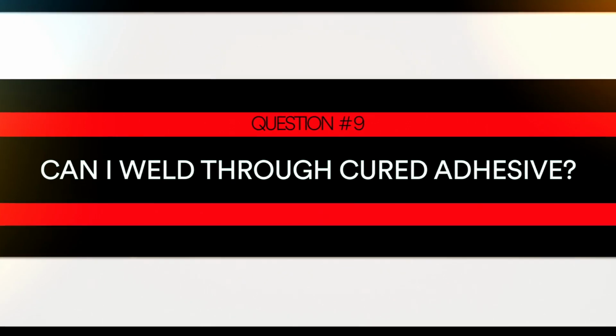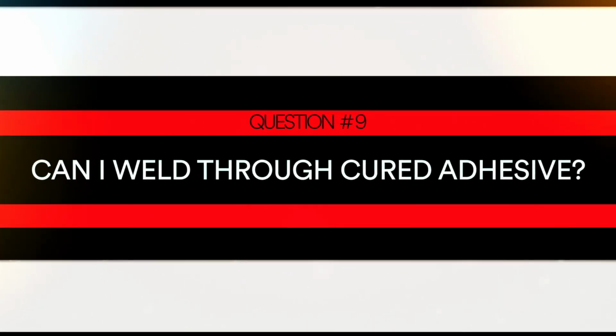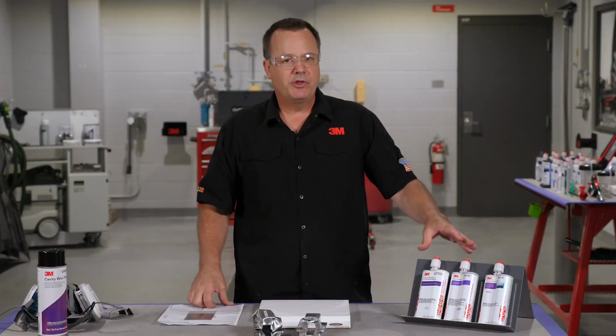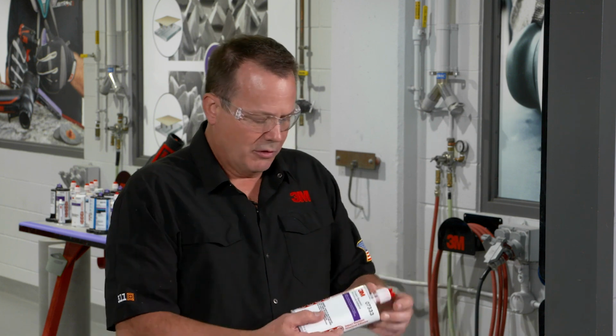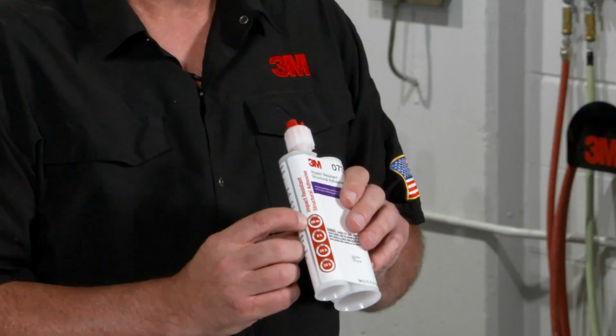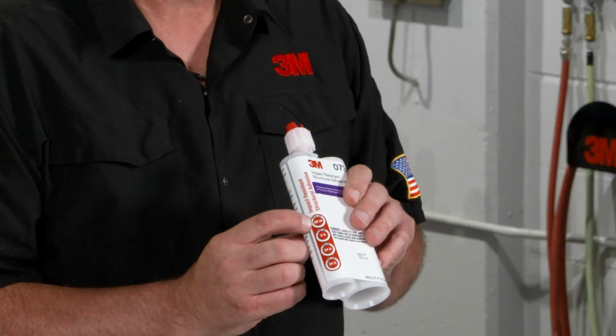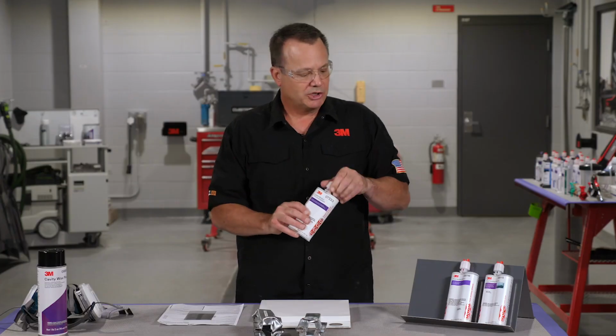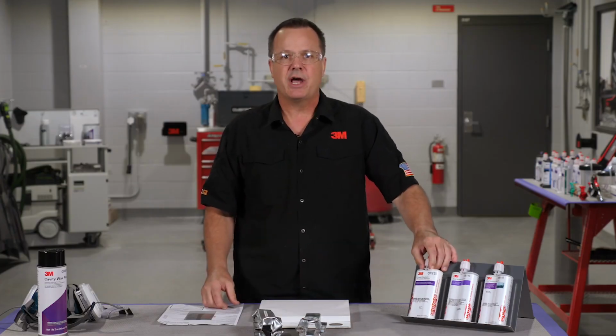Okay, number 9, can I weld through cured adhesive? 3M does not recommend welding through the adhesive after it's cured. It's really important that we follow the work time on the adhesive cartridge. In this case, it says 60-minute work time. You really want to get your welding complete within that work time.